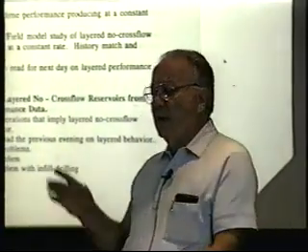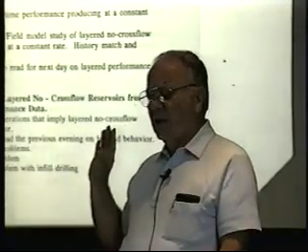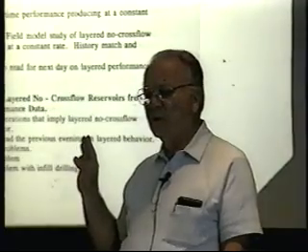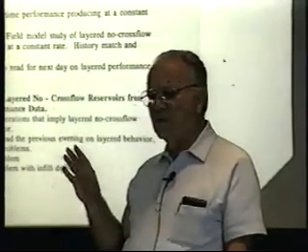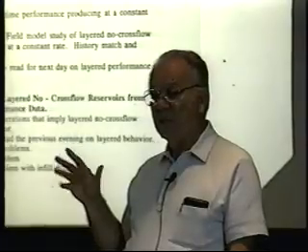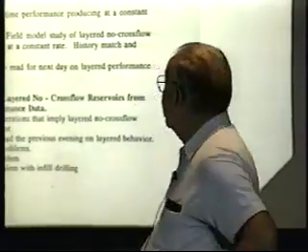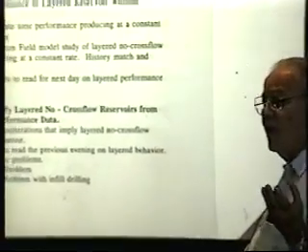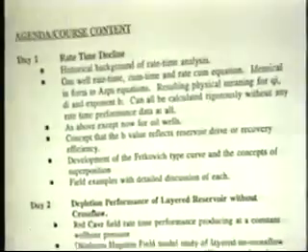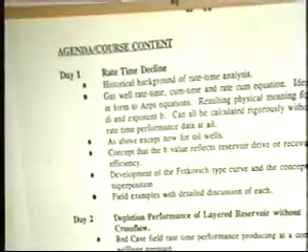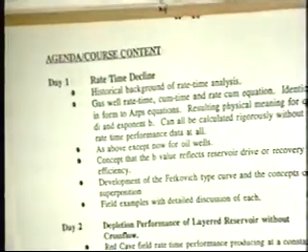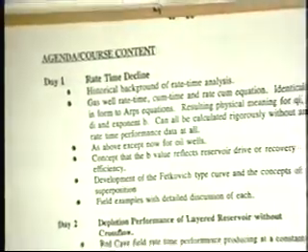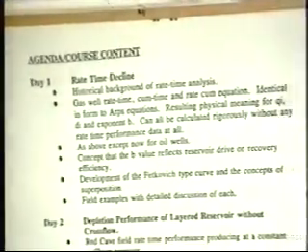And even though it may seem like we're talking about individual wells here in a lot of situations, the whole analysis procedure, the concepts apply to fields, the total field. Some of this will come out that will define or try to explain what the variables in the Arps decline analysis equations mean. The D sub i is nothing more than the gas or the potential of the well divided by the gas in place. That's all it is.